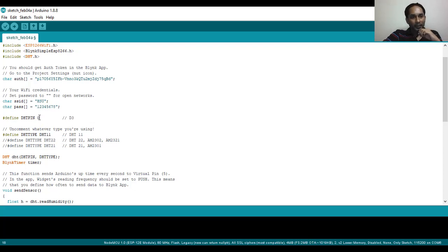See, pin number 0. This pin number 0 is actually for your Arduino, and Arduino pin numbers will be different from ESP. So I have one on the internet. If you search Arduino pin and ESP pin, it will give you a list. So this is the pin number for Arduino, and for those pin numbers, you have D0, D1, whatever, it will show you there.